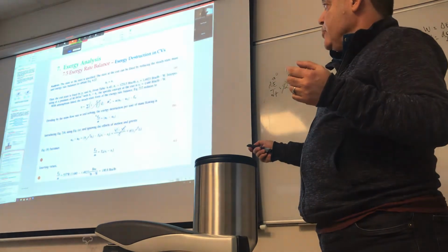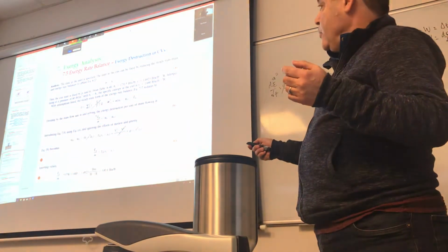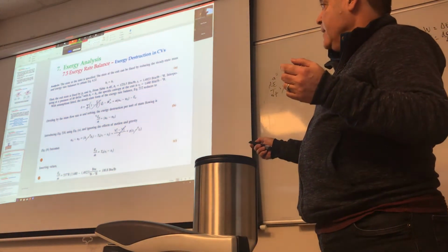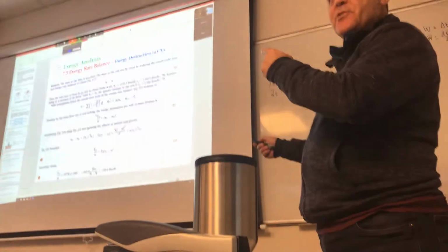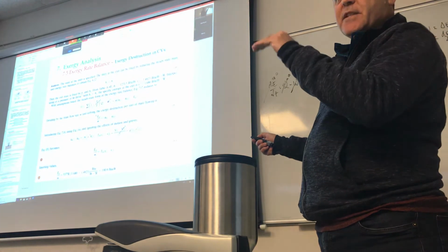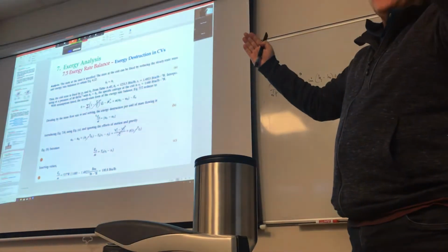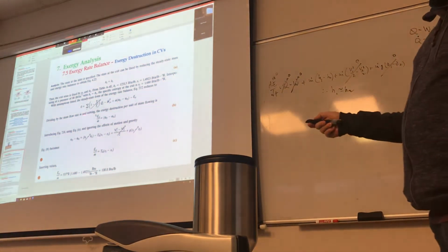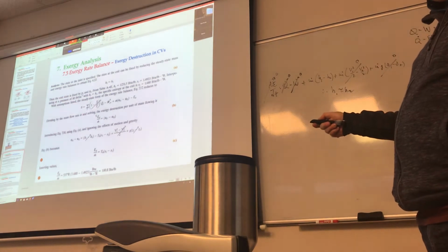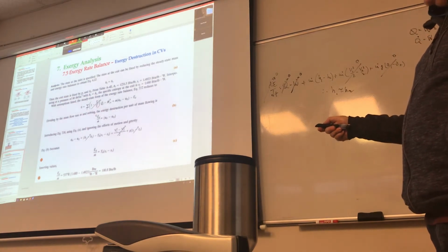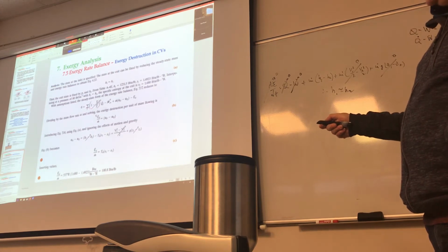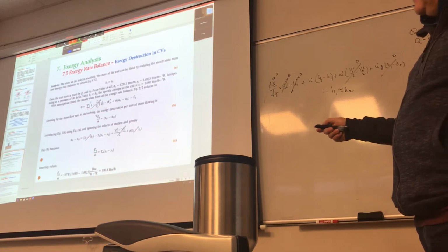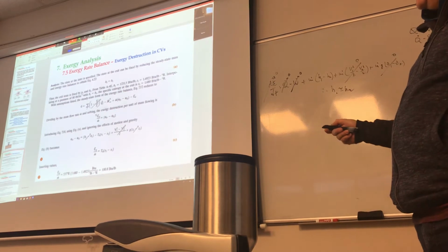This is the exergy transfer by heat, exergy transfer by work, plus m dot exergy flow in minus exergy flow out minus exergy destruction. So a perfect example that shows that longer equation that we talked about. Steady state, it's 0. Anything about the heat transfer? There is no heat transfer, so this term is equal to 0. What am I talking about in here? There is no work, this is equal to 0.